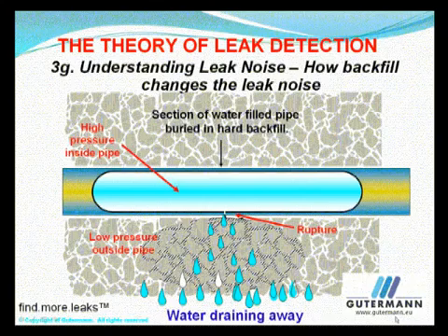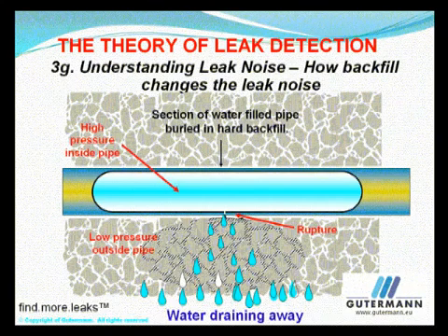The effects of different soil types. There is a large differential in pressure between the inside and outside of the pipe when the backfill allows the water to escape rapidly. So this leak noise will be loud, clear, and high frequency.